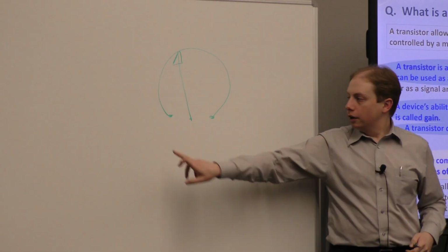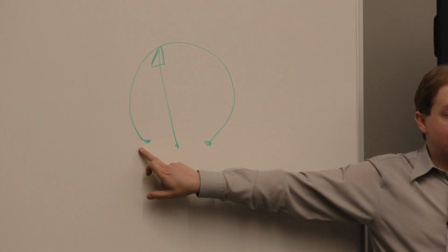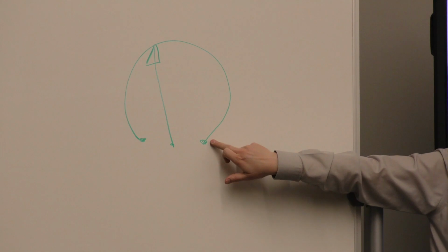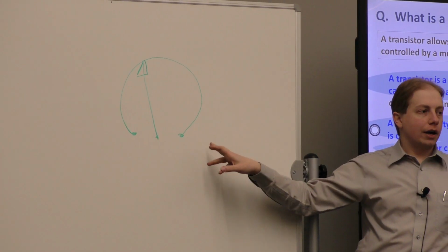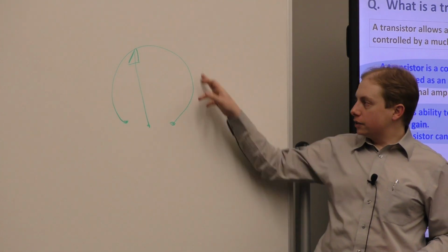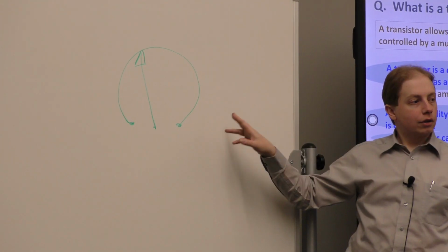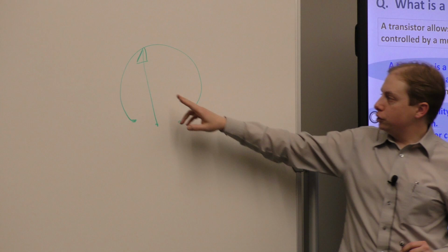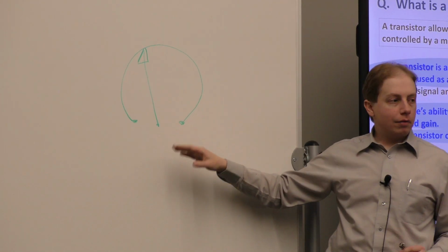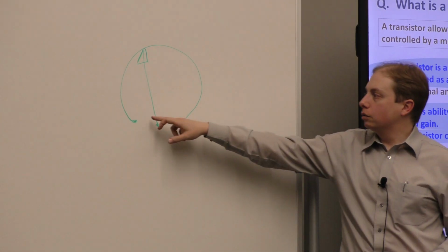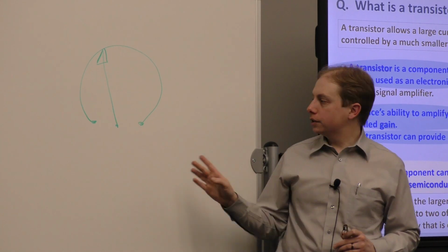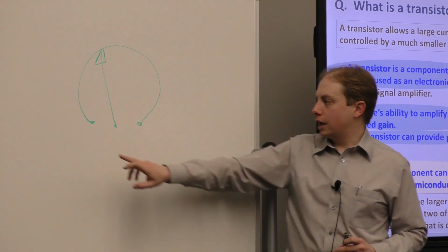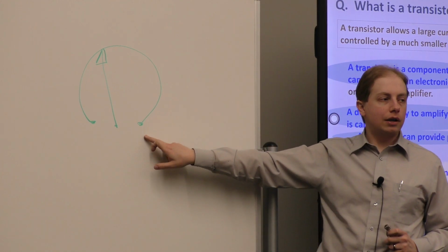Okay. If you put a voltage here on this side of the resistive element and you ground the other side, then you've created a device called a voltage divider. What that does is that sets up a fixed current through this device. And so as you move that wiper, now you have a variable voltage depending on where you move that wiper across this circuit. But it takes 3 terminals to do it because you have your voltage on one side and you have a ground reference on the other side.